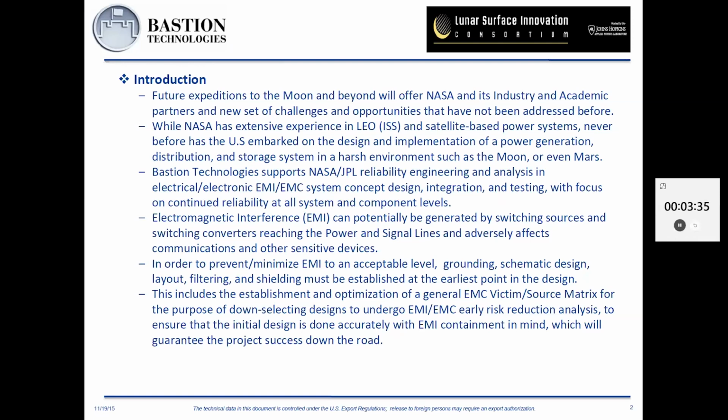This also includes optimization of a general EMC victim-source matrix for the purpose of down-selecting designs to undergo EMI/EMC early risk reduction analysis, and to ensure that the initial design is done accurately with EMI containment in mind, which will guarantee the project's success down the road.